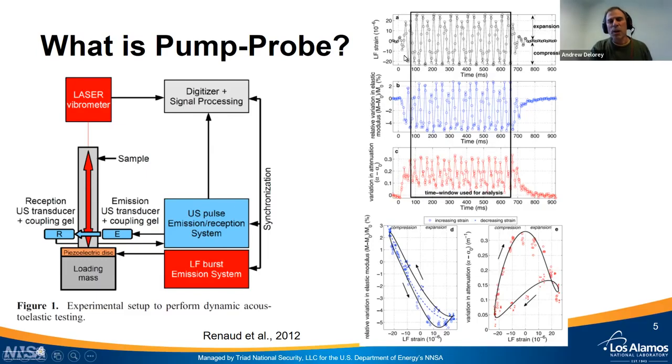So when you take the top two, the measurement points in strain and elastic modulus, then you can plot them on an axis that has strain on the horizontal axis and the fractional change in modulus on the vertical axis. And what you can see is, if this were linear, of course, this would all be just a horizontal line. The modulus would be insensitive to strain, but that isn't the case in rocks, and that really isn't the case in most materials, especially things like rocks.